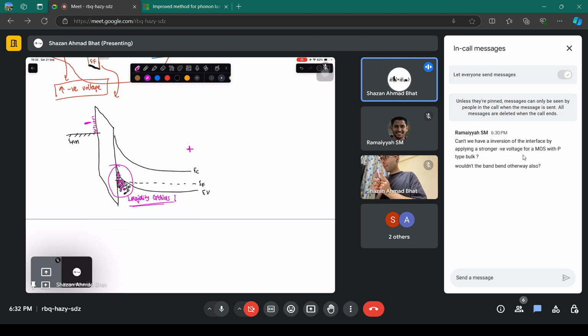Second thing is, if you go beyond that particular voltage, this oxide can break down and the device is damaged. What is breakdown? There is a particular threshold of electric field that an oxide can sustain. If the electric field value surpasses the breakdown field, the oxide breaks down and you get a flow of charge in this direction.